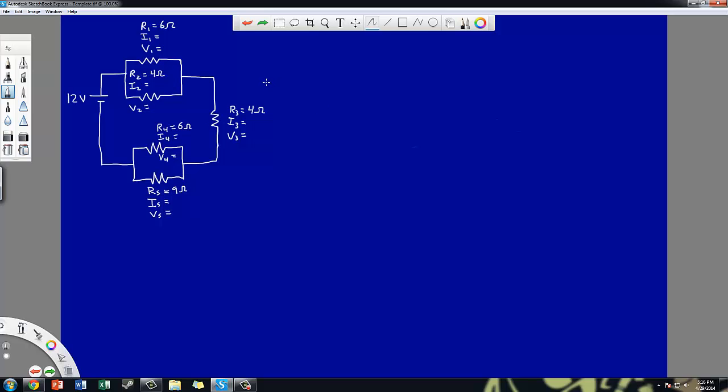And so I'm going to go ahead and combine those. Just as we did before, I'm going to say that this is parallel, and I'm going to mark that it's R1 and R2 that I am combining. I'm going to redraw this: 12 volts and 1 combined resistor now at the top. Still have R3 off by itself, and I still have R4 and R5 down here at the bottom. It's okay to draw this a little bit smaller, because the important part is just staying organized with what I'm doing. So I'm going to call this R1,2.